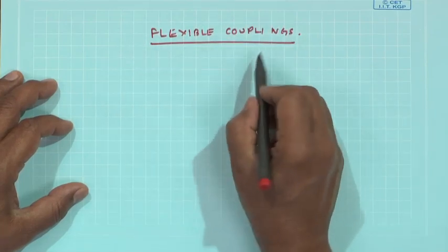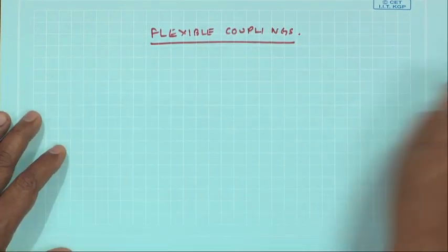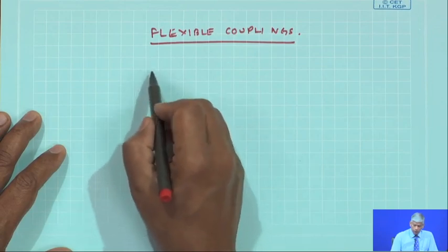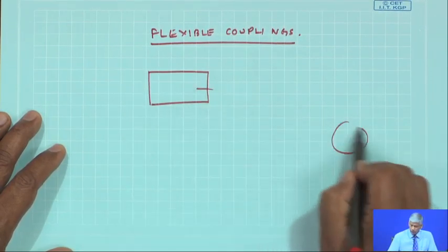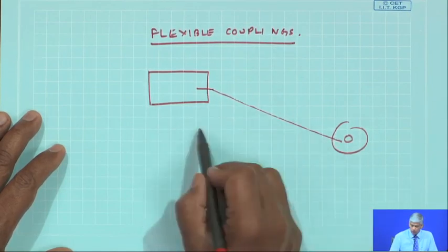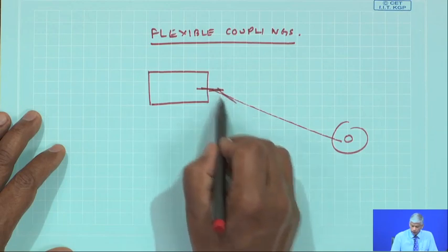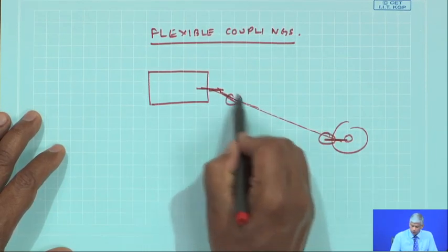Okay. The helical couplings and so on, gear couplings, etc. But in an automobile, we have a shaft or an engine here and a differential here. So, there is a large angular deflection. Okay. So, they put what is known as a Hooke's joint.